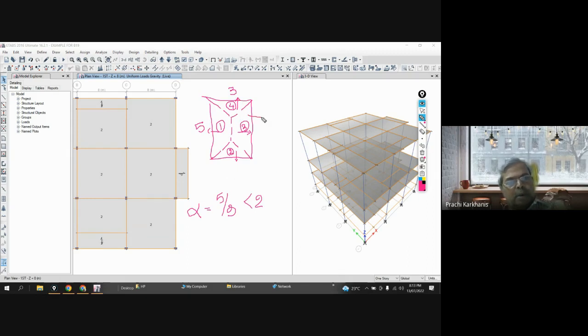And there are two-way slabs. So if you go for two-way action, okay, you will see that this is, I will call, let's say this is the triangle. Then this is Lx by 2, whatever is Lx. Lx by 2, this is also Lx by 2, then this is also Lx by 2, and not Ly by 2.